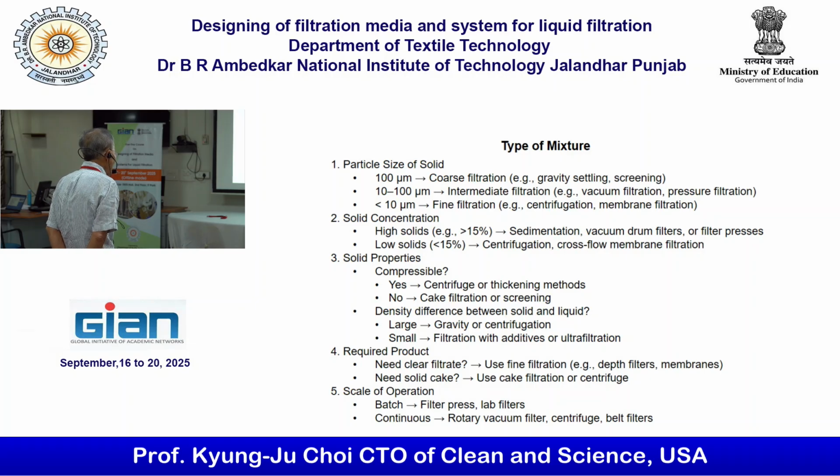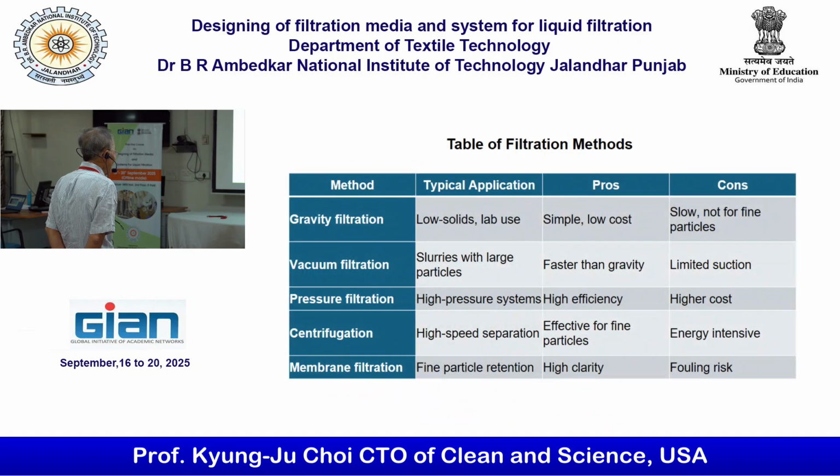Required product, what is your product? The filtrate or solid. So if the final product is solid, then the cake is quite important. Scale of operation, batch or continuous. Filtration method: gravity, we already covered that one. Vacuum, pressure, centrifugation, membrane filtration.